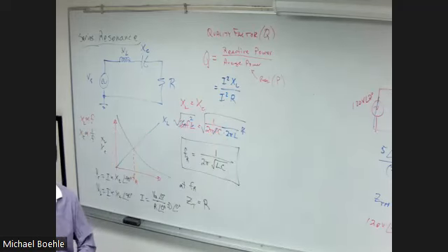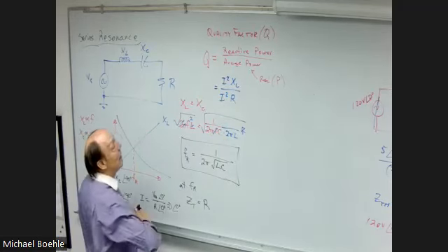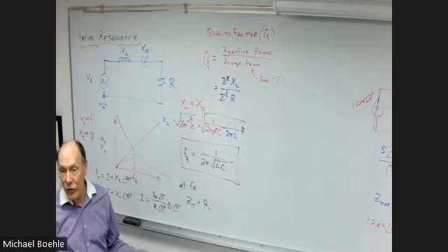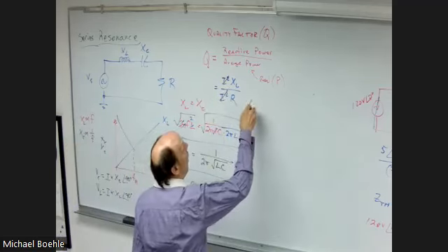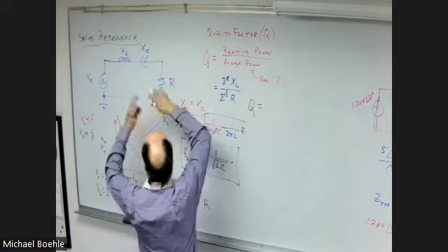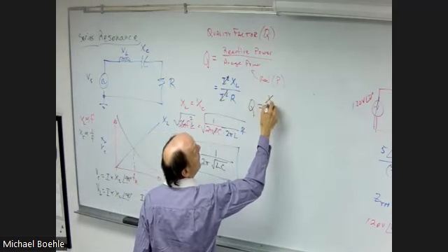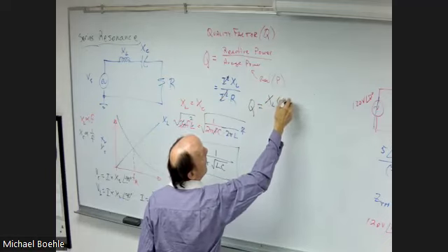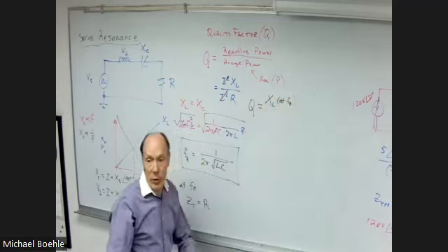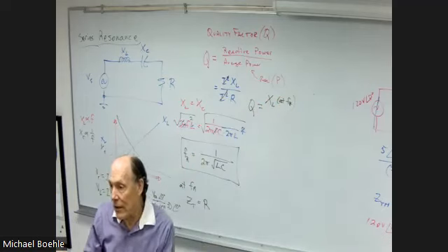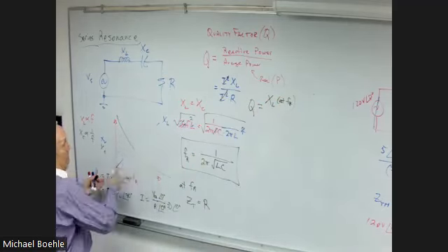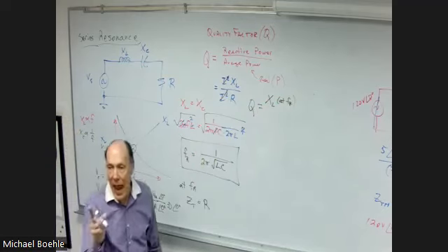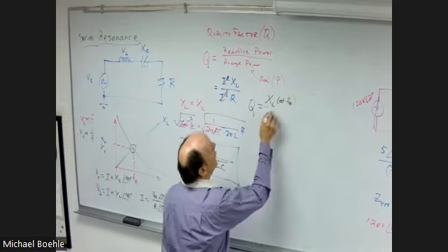Well, the beauty of a series circuit, of course, is what? Current is the same. So it cancels out. And so the quality factor of this circuit is the inductive reactance, and I'm going to qualify this at resonance, because we know inductive reactance changes, right? We're talking about that level right there, at resonance, divided by R.